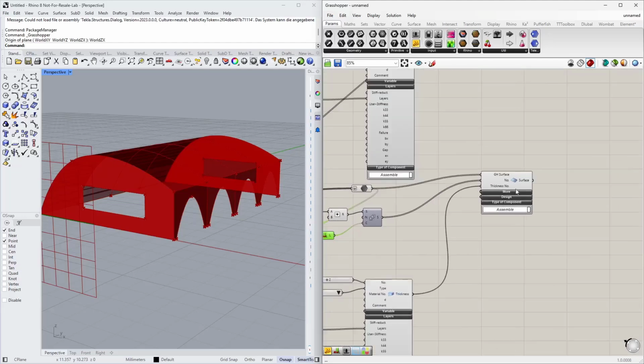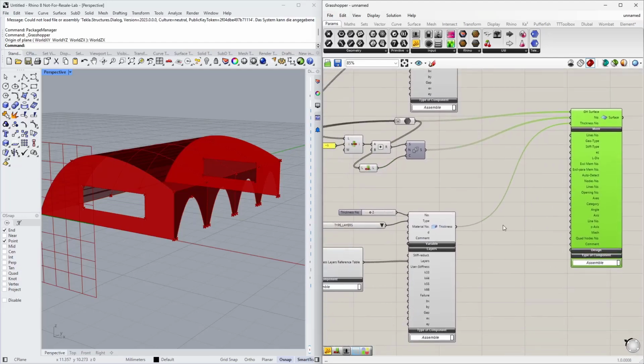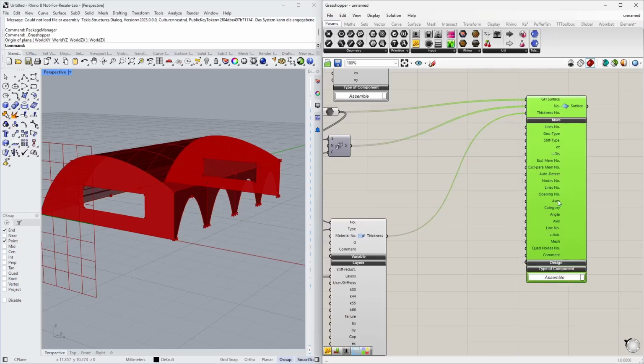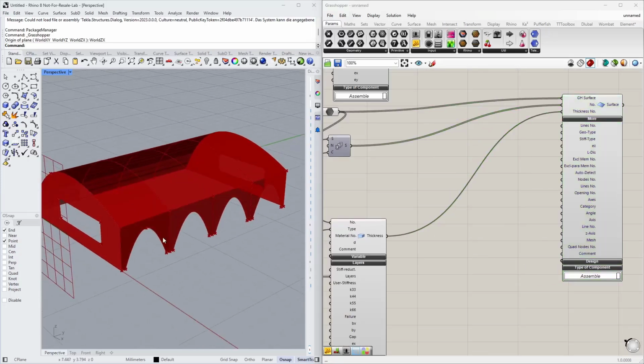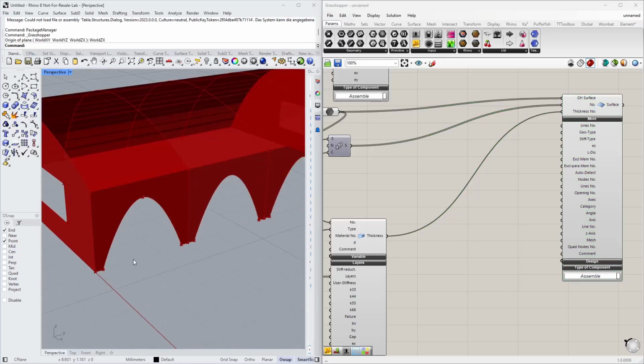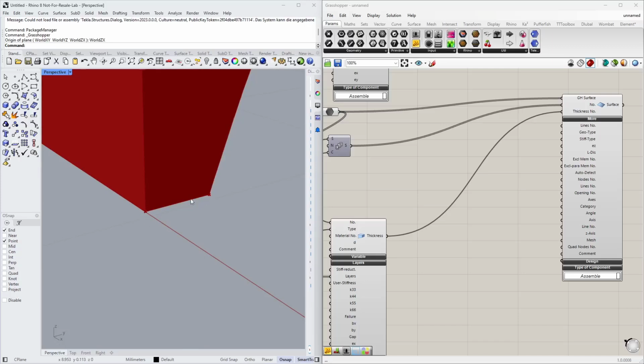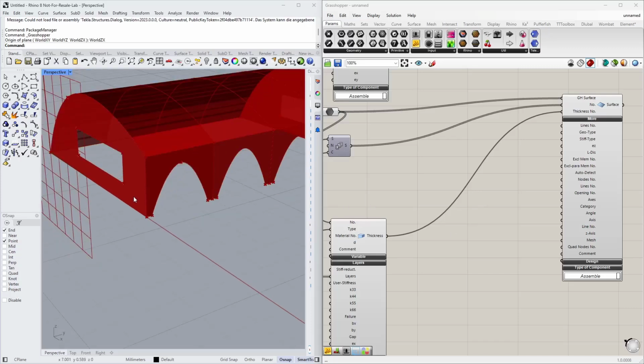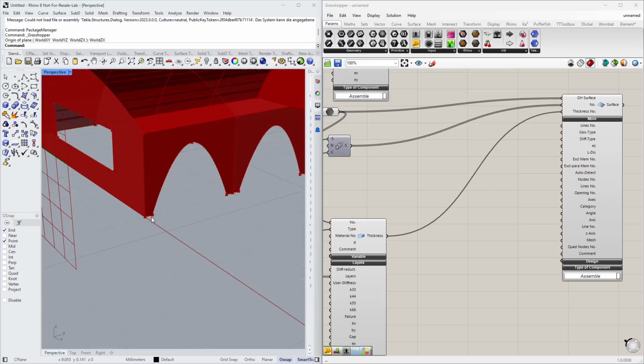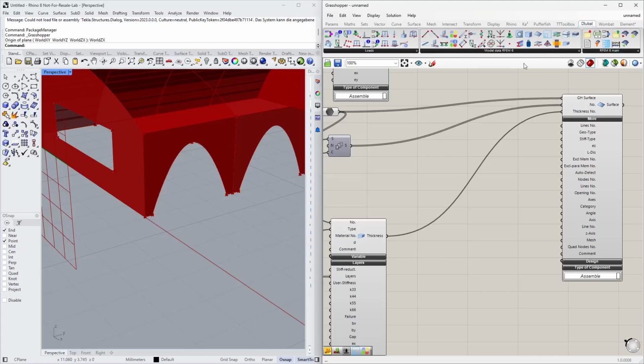That's good. All right. One more thing that I would like to define in here is a mesh refinement. Why? Simply because the default, the global FE mesh length is 0.5 meter. We have here a distance of, what did you define, about 0.3 meters. So let's have at least 3 elements over this length here. So I would like to use a FE mesh for those wall surfaces, or FE mesh length with 0.1 meters. Therefore, we have these mesh refinement components.